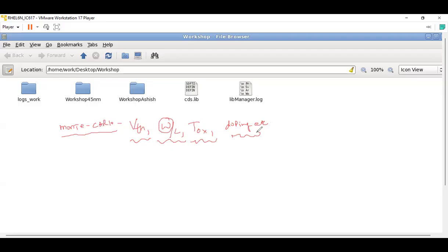44.95 nanometer. So these kinds of variations are possible. You say that I'm using 300 nanometer width. If it is possible that during manufacturing it becomes 299 nanometer width, then what will you do? Similarly, when you dope your PMOS, the default doping concentration is giving some value in your simulator, and you actually end up with 5%, 7% lesser doping, because in manufacturing you cannot create a 100% ideal device. So that is why it is very important that you simulate your device with all these different conditions.